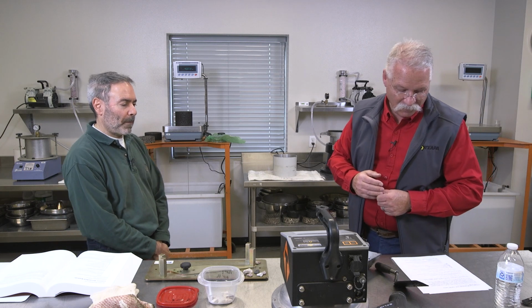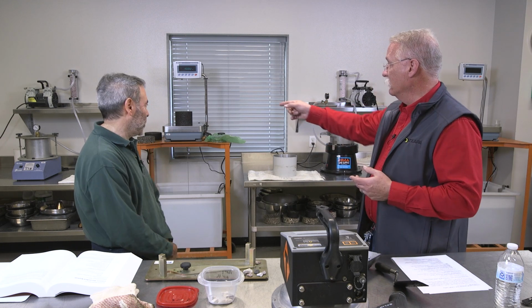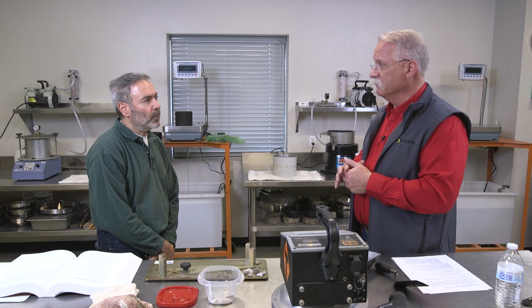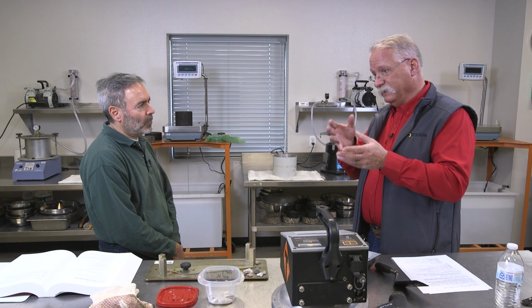Good deal. So we're going to sample before, during, sometimes even after construction, where we're taking cores. You've got a core there on the table. We're going to measure the in-place air voids and make sure it meets our standards, our specifications, so we get the right level of density, so we get the right level of performance. And in-place air void and density is tied pretty well to performance.